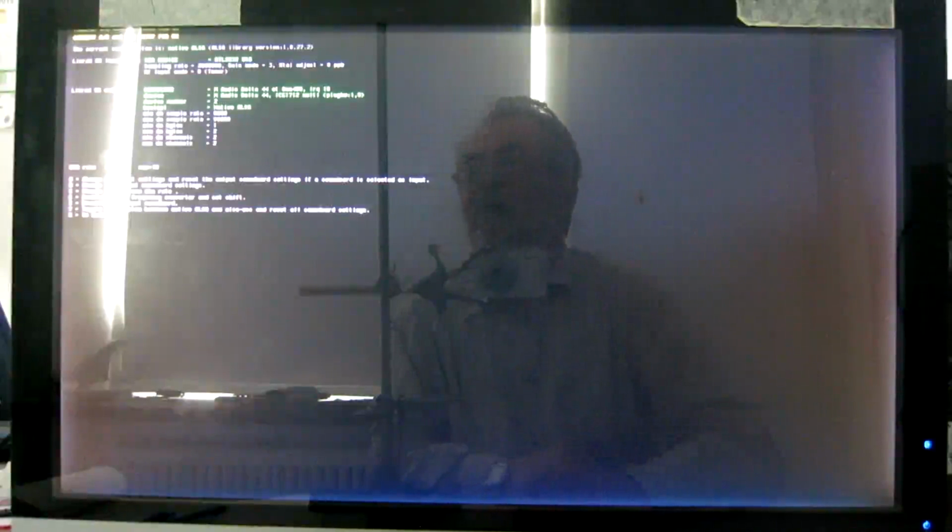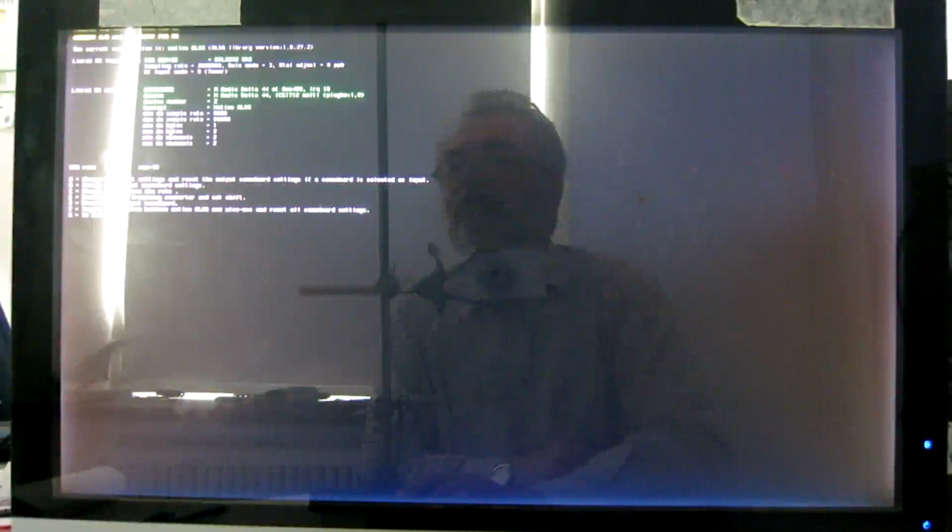I can now show some of the factors that affect the CPU load. XU. Here C, that controls the sizes of the buffers. They are now set at the lowest possible DMA rate. That is 10 Hertz. It means that the buffers have a length corresponding to 0.1 second. So I changed that to 100 instead.